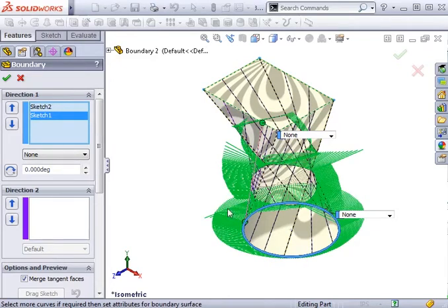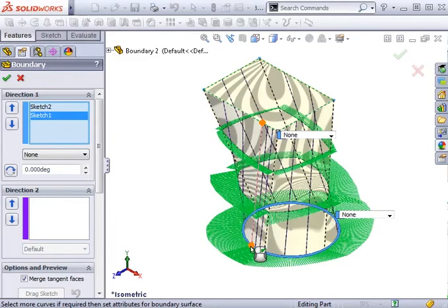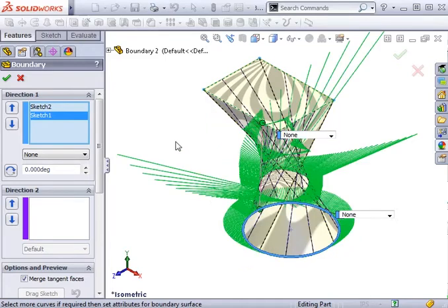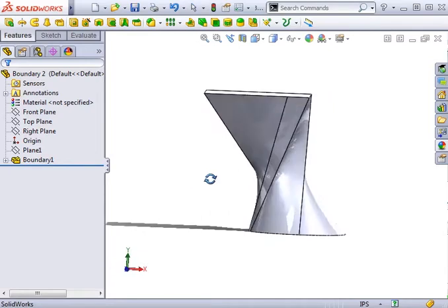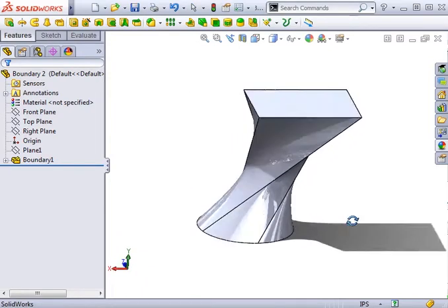But if you need to create more complex shapes, one feature over another may create nicer surfaces in addition to the increased control over transition and edge curvatures. Because of this, I would recommend experimenting with the different features, and over time, you'll be able to quickly decide which feature will be the most appropriate for the design you're working on.